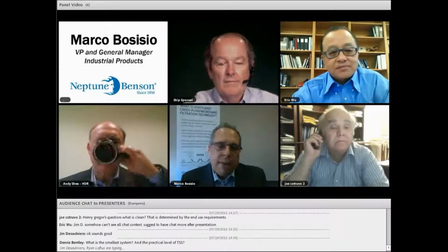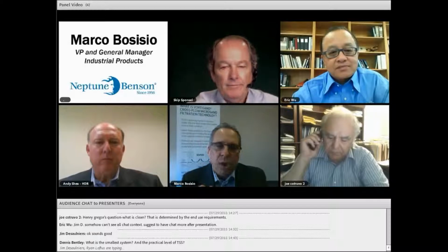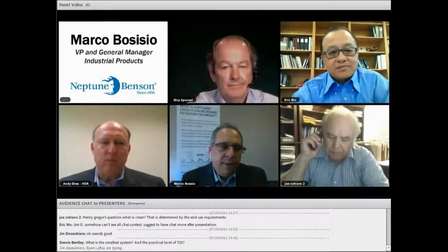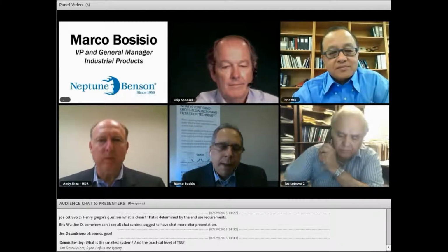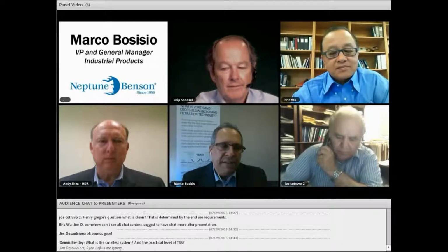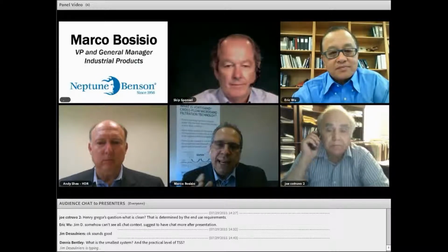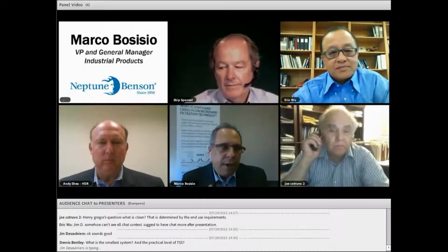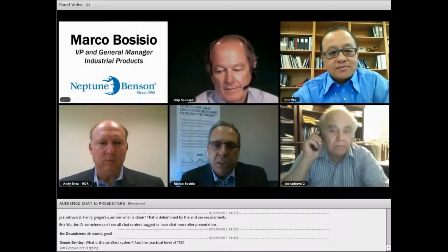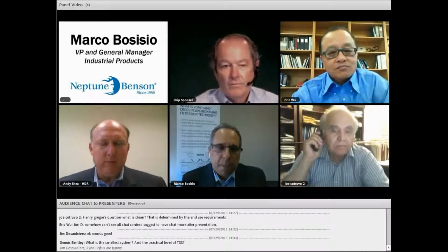But we do have some systems like air scouring that are available to make sure the media is always clean, even if there's some BOD in there. But I would say that if a designer believes that a regular multimedia filter or a disc filter can handle the type of effluent that is trying to be filtered, then our system will definitely take it as well. Thank you. Andy.